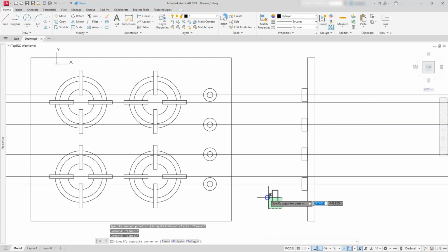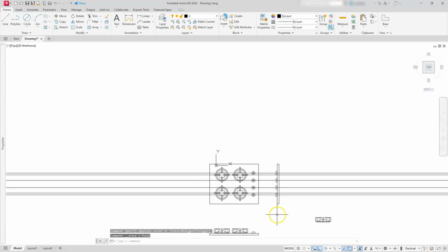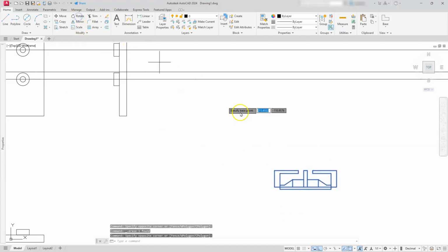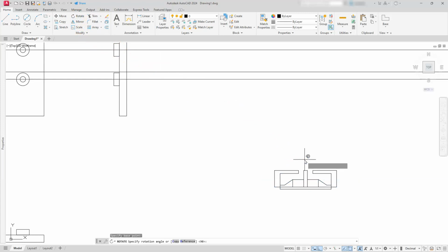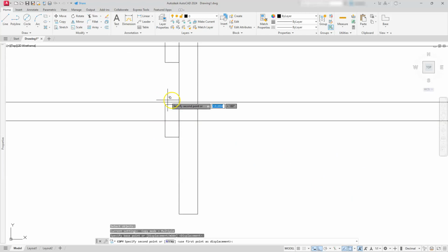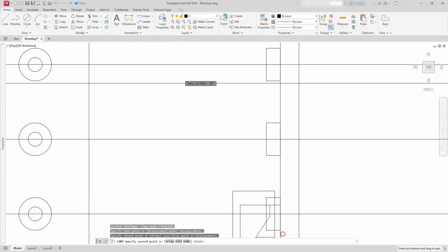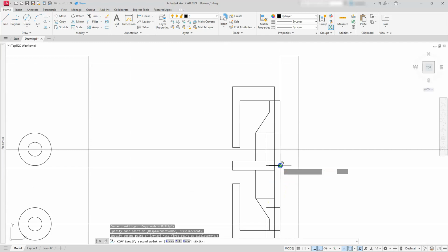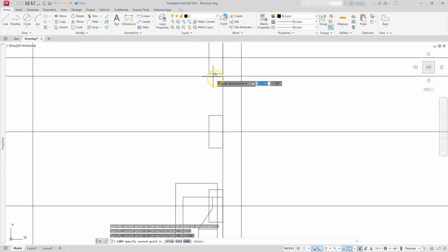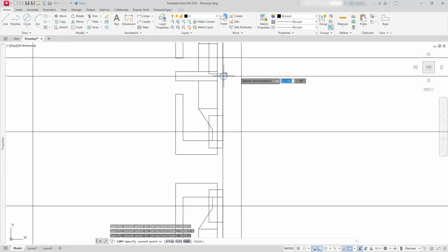All right. Now I can erase this one. And then we're going to take a look at this, and we're going to rotate this as well. So I'm just going to rotate it, select it, go to a base point here, type in 90, copy. And then I'm going to copy it from this midpoint to this intersection. And we have one more intersection here, which is located not there where I selected. Let me undo that last one and place it at this intersection right here.